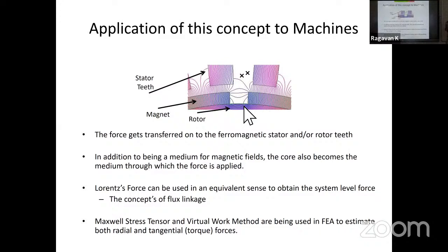Instead of that shaft, if I use the insulating material in the slot for the winding, then what will be the behavior of the fields around that winding? That's for a slotless motor. So there is no tooth, so there is no path for the lines to flow from there. Let me rephrase the question. There is no stator tooth. The windings are placed at some other plastic surface. They are tied to some non-magnetic plastic surface. Yeah. So these kinds of machines are there. They're called slotless machines. They are being used in very high speed machines.